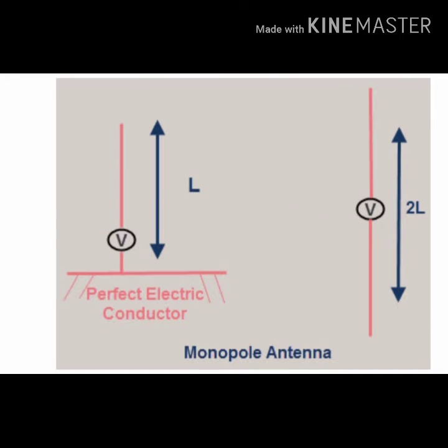Monopole antenna. A monopole antenna is half of a simple dipole antenna located over a grounded plane, as shown below. The radiation pattern above the grounded plane will be the same as the half-wave dipole antenna. However, the total power radiated is half that of a dipole. The field gets radiated only in the upper hemisphere region. The directivity of these antennas becomes double compared to dipole antennas.